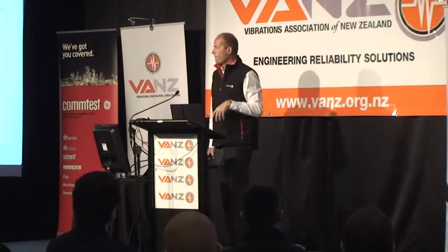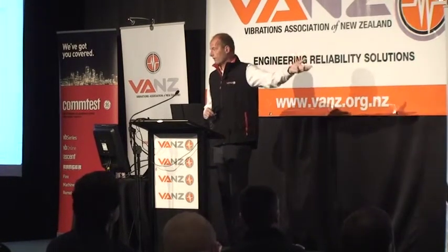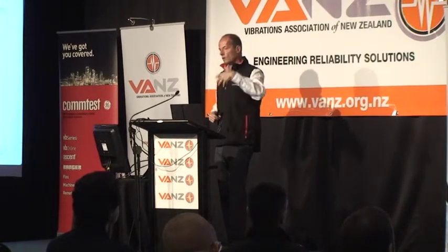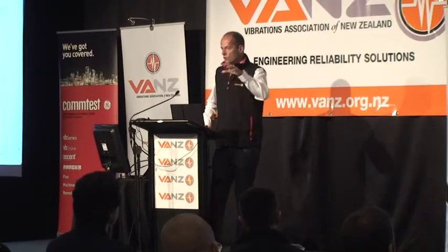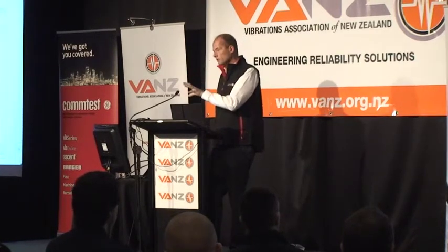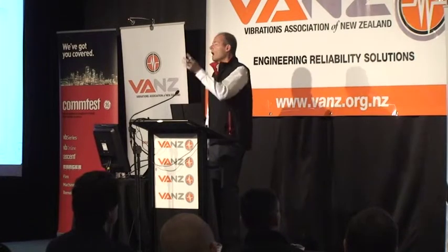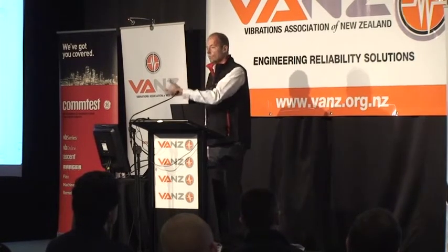There's a lot of things to think about, but there's condition monitoring tests for all of this that we can test to make sure the lubricant properties are okay, the viscosity is okay. We can check for contamination. We can check for particles that might harm the machine, and we can see whether there is wear occurring.